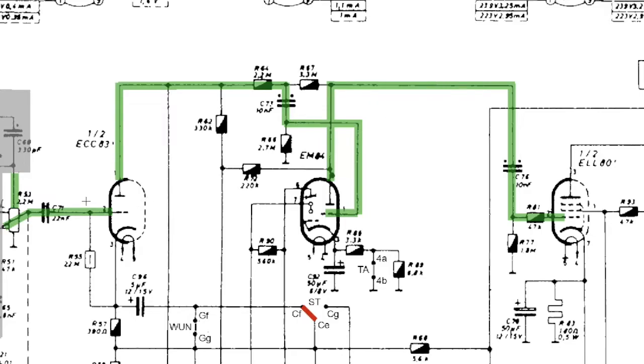So what we have now is this signal going through there, through there, through there, driving that tube. There is one other thing that needs to be looked at here, and that is this triode. Obviously, part of the biasing of this triode is that it needs a cathode resistor, and it does have one. This is the cathode resistor here. It actually goes through that.